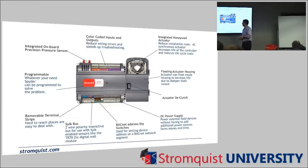These are pretty interesting little things right here: BACnet, address dip switches, and Silk Bus. So BACnet we're going to talk about in a little bit, and you'll notice that anytime you're doing anything with BACnet, you can always tell if it's a BACnet controller because it's going to have little dip switches on the controller. So that's how you can seem smarter than other folks: look at it and go, oh, that's BACnet. And they're looking all over the place and it doesn't say BACnet anywhere on there. Well, how the heck did you know that? Well, that Rob guy at Stromquist in that intro to DDC class I took 5 years ago told me if it had dip switches on it, it was BACnet. So Silk Bus is a proprietary COM bus that we're going to talk about in a little bit.